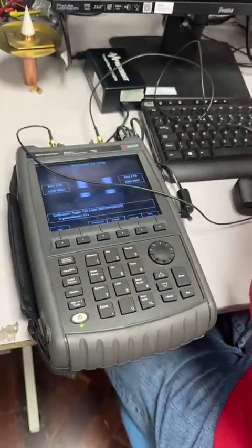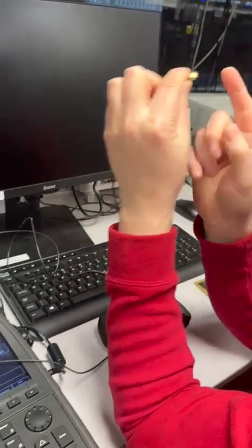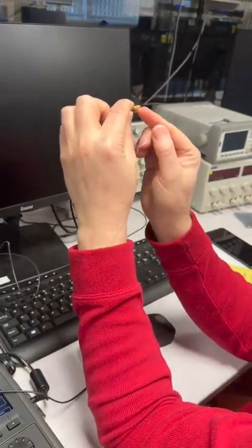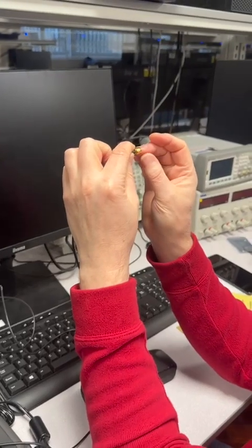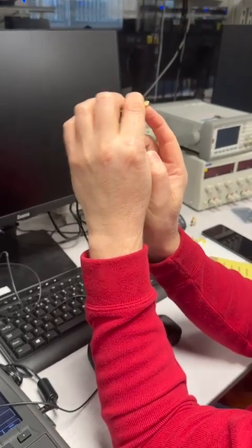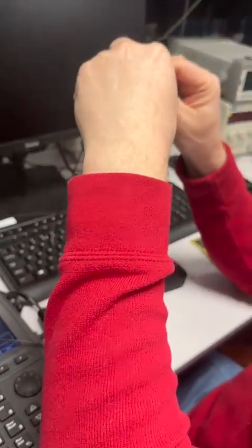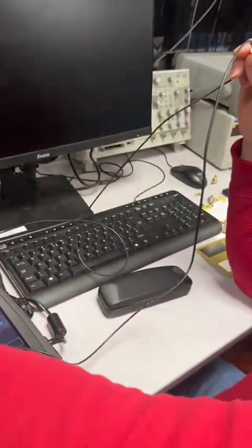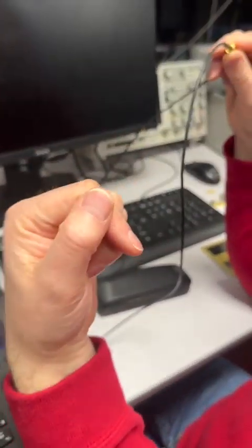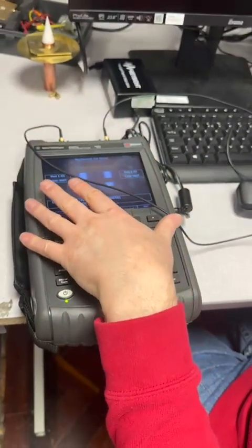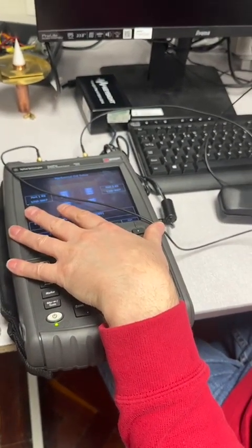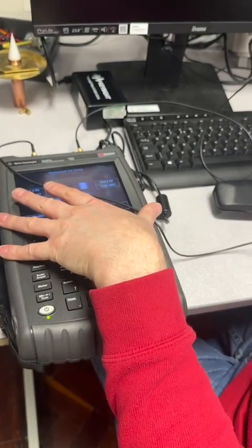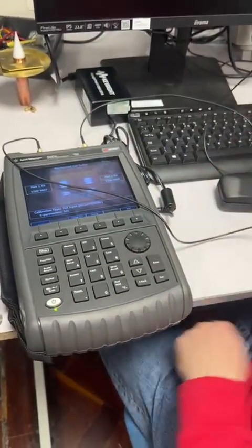Okay. So when you do the load, you are looking at the standing wave along this cable to this interface. And through clever matrix mathematics, all of that information for the short and the open circuit, it cals to this interface. And when you put the through in, it's basically telling you the loss through the entire transmission path, backwards and forwards for S21 and S12. And then it's all done through matrices inside this instrument. It probably is a DSP function that's doing it all. It does all the matrix mathematics, and you end up with nice flat lines for everything.